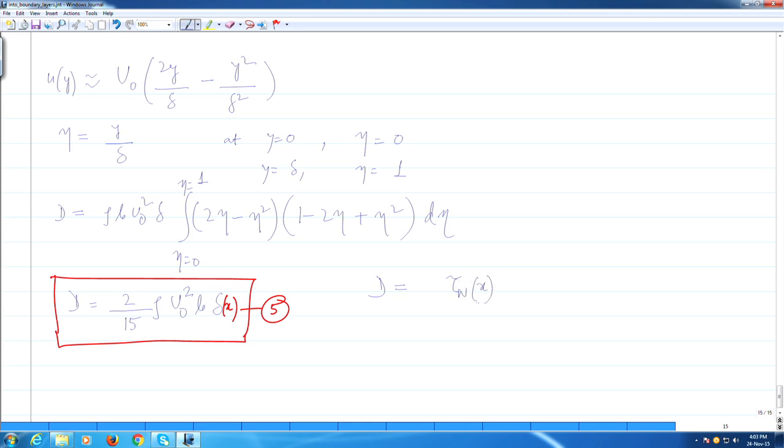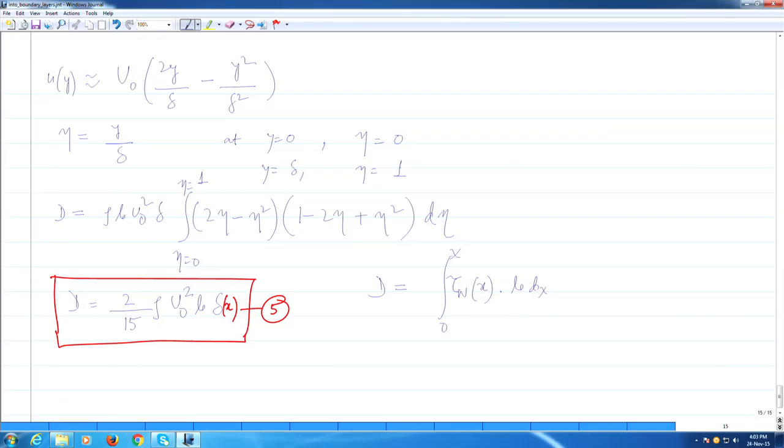It is the wall shear, right, it depends on the x. Okay. So, b and d, b is the width. Okay. So, this is tau w(x). So, we integrate that over the length x. So, a certain length x, right, will be responsible if you sum up all the shear forces, the entire shear force which is exerted on the length x, because the shear stress will depend on the x, right.